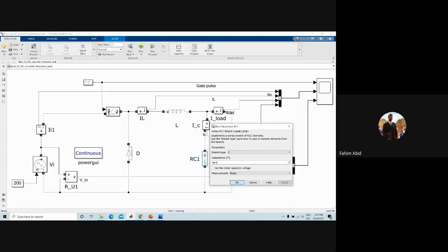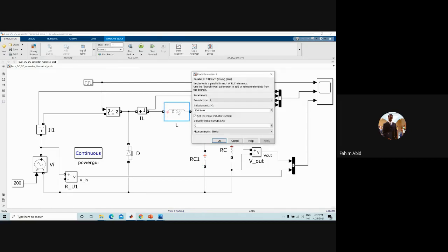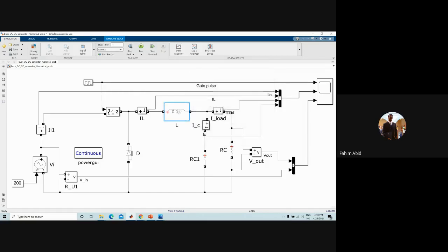Also, for continuous operation, you may have to have a certain inductor current. Now let's reduce. In the last part, it says that if we reduce it by 10 times, we'll have a marginal continuous conduction current mode, and if we reduce it further, we'll have a discontinuous operation.